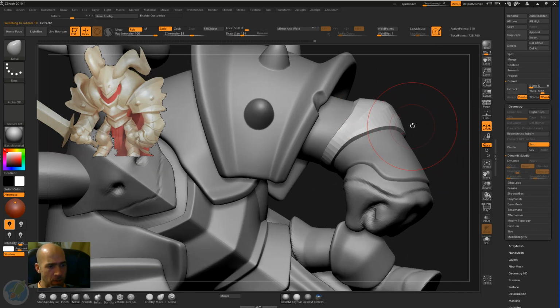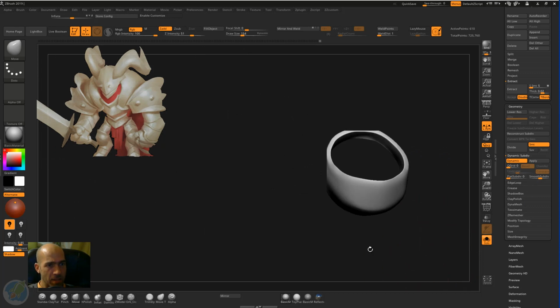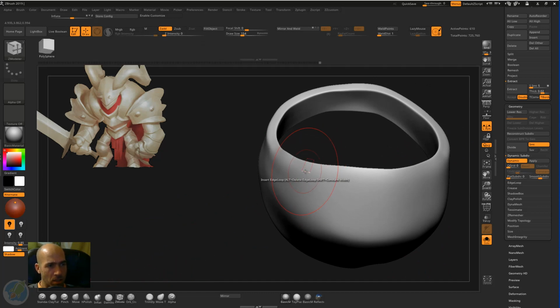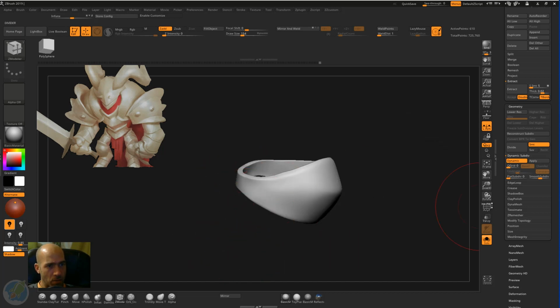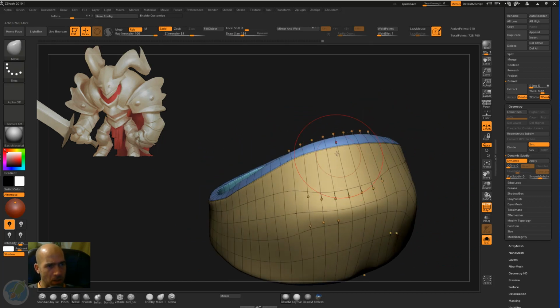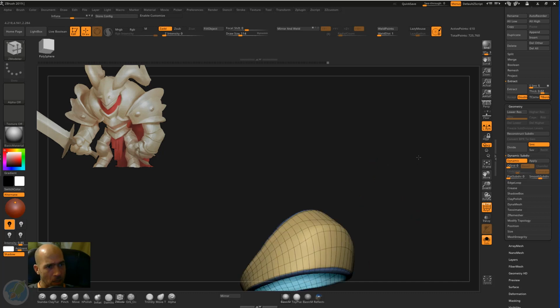It will be more consistent. It's looking good. Now this, press D, then crease at 1 crease level. Okay, dynamically subdivide at 3 or 4. 4 is nice. Then let's see this. And since this is not subdivided, this is not creased, we'll go ahead and crease it manually, just pressed here. And it's creased now. It's looking good, although we can put one more polygon probably here, but yeah, let's not get over ourselves. I think it's fine. Probably here we need to crease it more, yes.